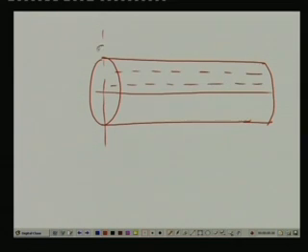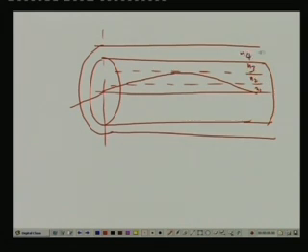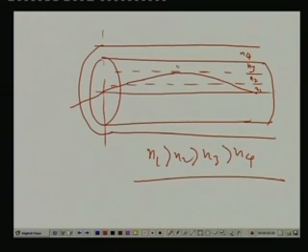Now, ultimately it is coming to the cladding. So, light will fall like this, it will bend again, and again, until it gets total internal reflection, clear. I can write N1, N2, N3, N4, so N1 is greater than N2, greater than N3, greater than N4. This is for visualization, to understand how the gradient index fiber works. It is not necessarily that all the rays will go to the core-cladding interface. In between it may have total internal reflection if the incidence angle is more than the critical angle, clear.